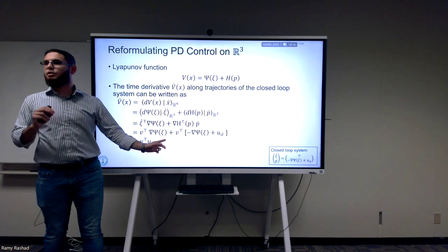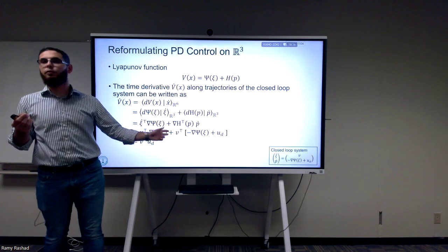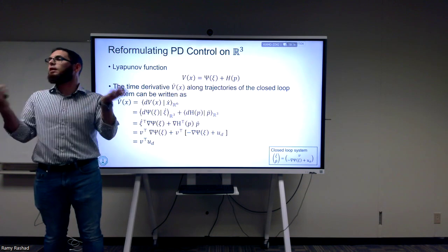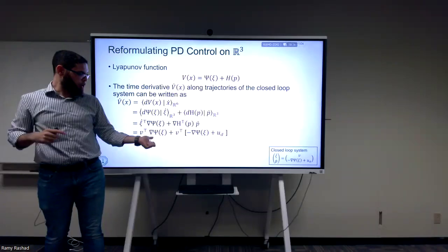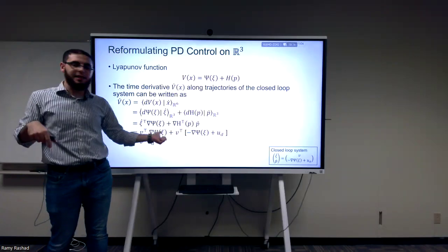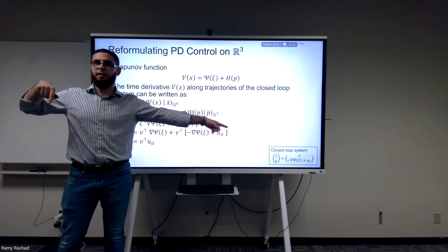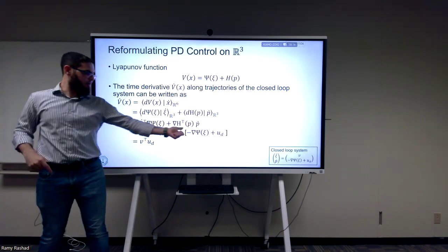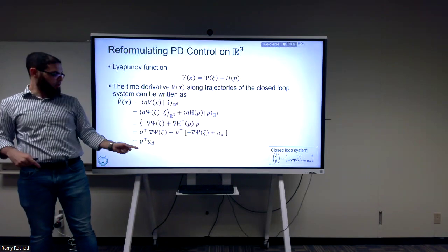So we didn't just generalize a PD controller. This is very powerful because it allows you to choose any function, not just the quadratic one, to get a proportional controller equal to kp multiplied by the error. You can choose any psi and choose u to be the gradient of it, and you're always going to reach this end in terms of the Lyapunov analysis.